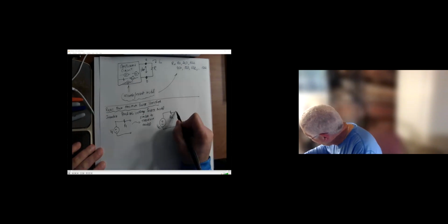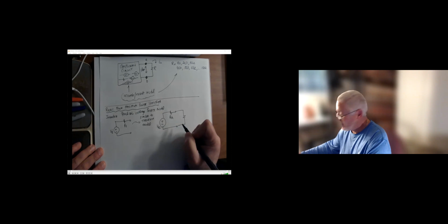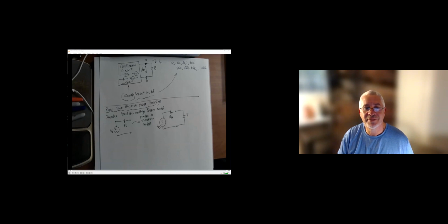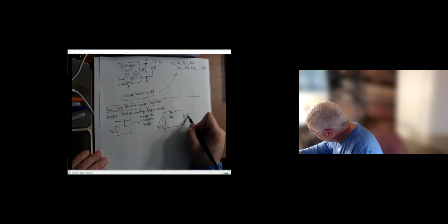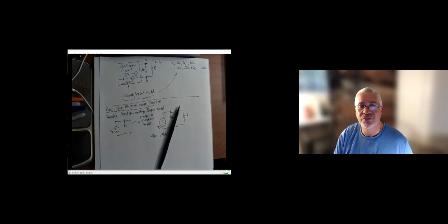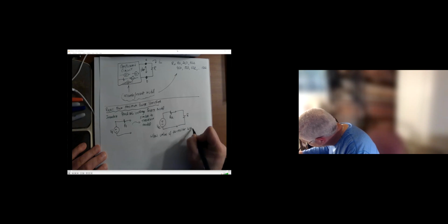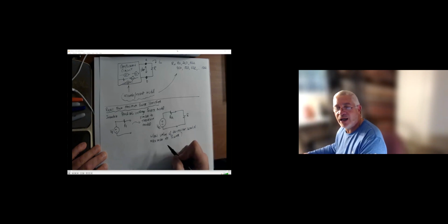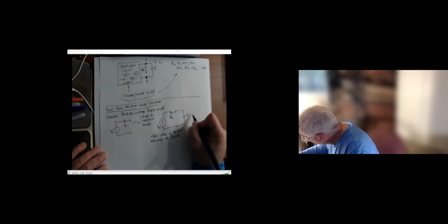So now, if we plug in a particular resistor, say R, and we ask what value of the resistor R would maximize its power, what we found out when we did the mini lecture on maximum power transfer is that the value is R equal RTH.